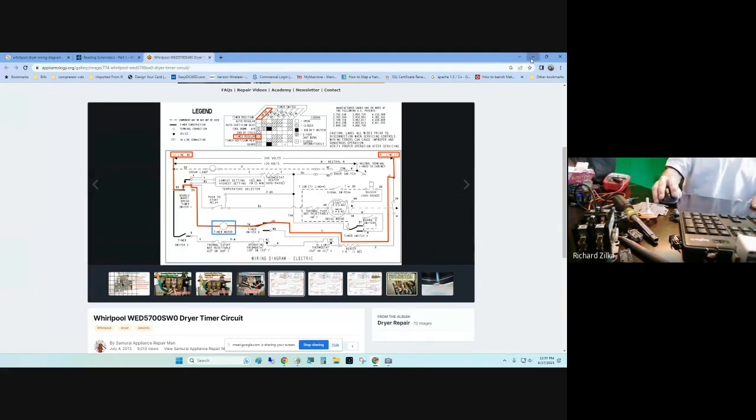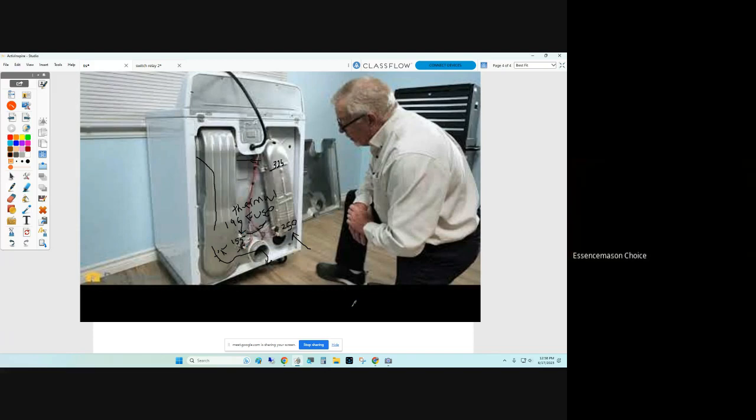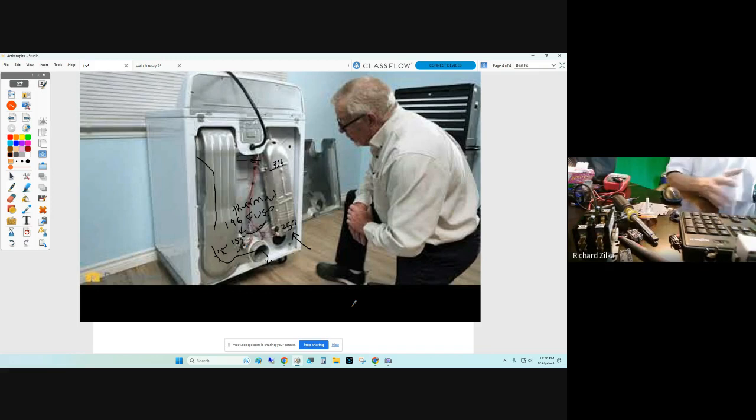Okay, but I was telling one of my students, okay, well, my operating thermostat's here, my thermal fuse is here. Well, why do we put this high limit here? We could still put it here if I want, right? Why is it here on the element and not way over here on the exhaust? Well, that's where the heat's actually getting made, over the element. True, but that doesn't explain why they put them in two different locations.